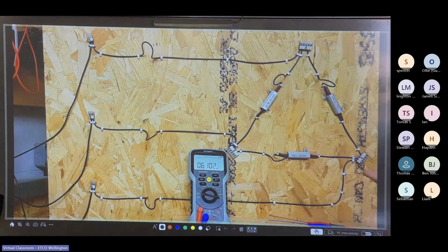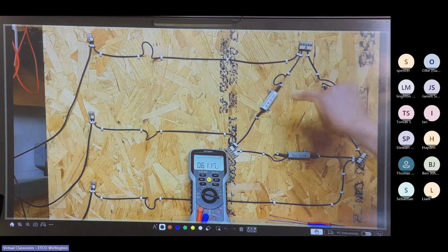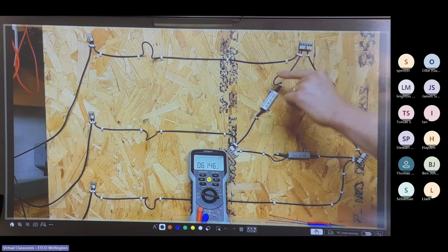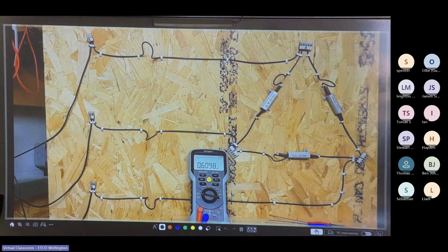But as you can probably see from those two numbers that we just measured, it's not a matter of just adding those two values together. We can't just double this value to get that value. There is a number that relates them to each other. And if you've already seen the start video, hopefully you know what that number is. So at this point, we're going to go over to the whiteboard. We'll have a look at a diagram of this, and we'll have a look at those all-important relationships between voltages and currents inside a delta connected load.